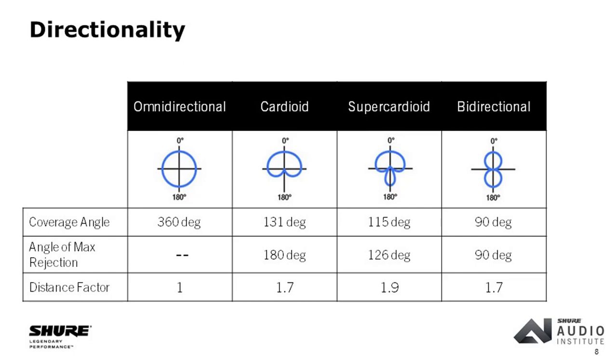And Gino, a lot of people are unfamiliar with this one. What does it mean? So one of the advantages that you see from the directional microphones is that they do a better job of rejecting unwanted sounds that are originating off axis from the front of the microphone. And what that buys you is better signal to noise ratio, the desired signal versus the noise level in the room, right? What the distance factor allows you to see is how much better of a job a directional microphone does of rejecting that unwanted noise.